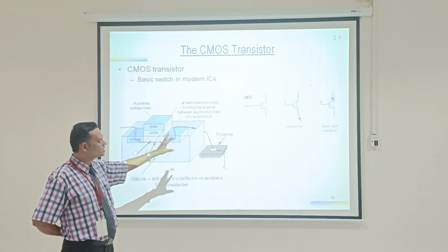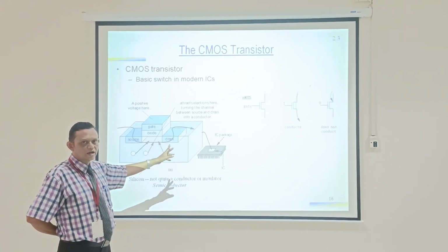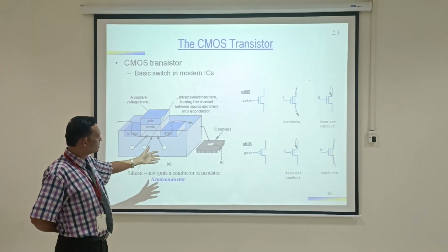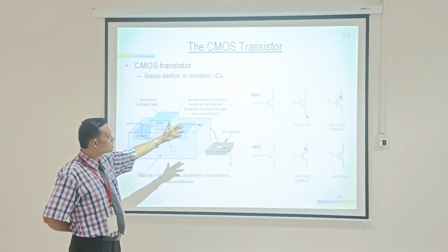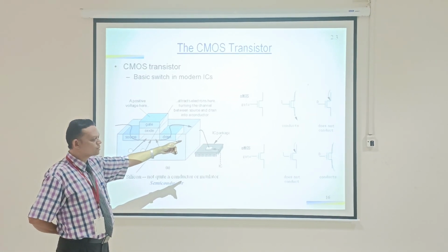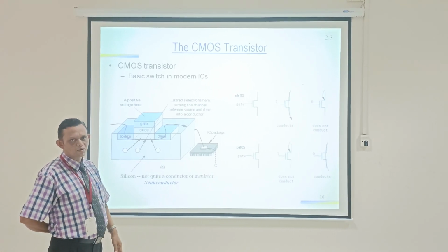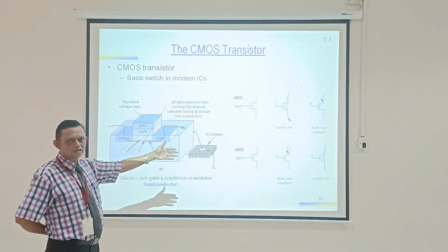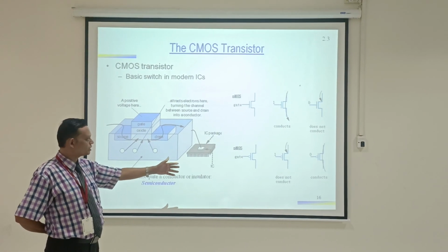First you should understand this concept effectively, so that you can better understand the concept of gates. Now, as I told, another gate is available, PMOS. It is directly opposite to that. In NMOS you have to provide 1 to operate it properly, but in PMOS you have to provide 0 to operate it properly, in the sense that you have to permit the flow of current from source to drain. That is, 0 volt has to be provided.